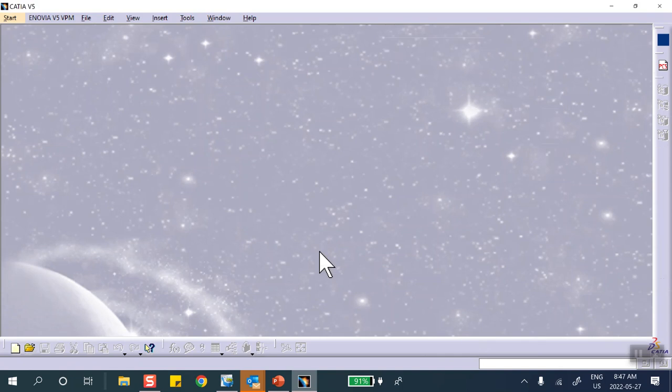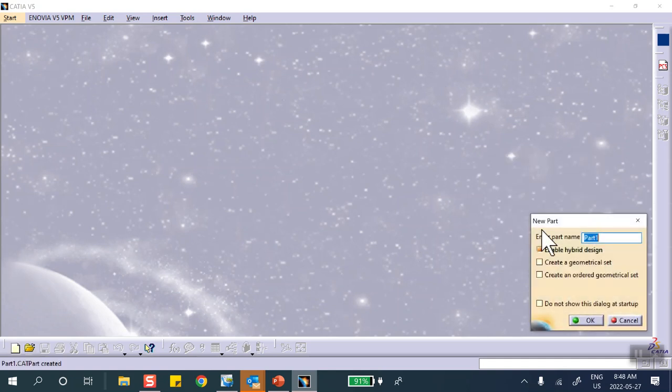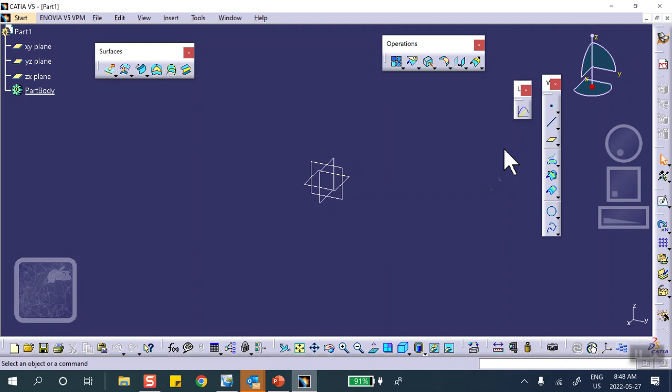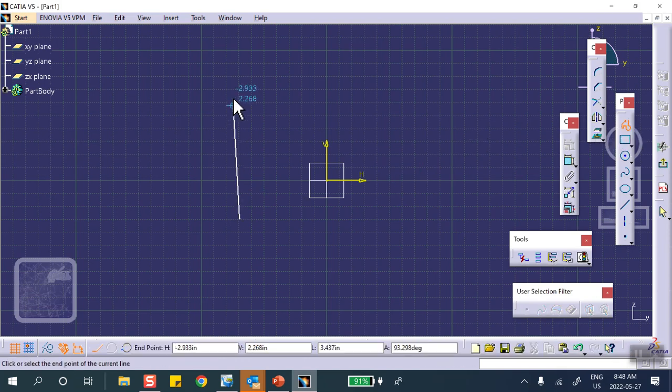Now, from this point on, I'm not going to worry about dimensions. I will just go make it. I'm going to create an extruded L, so that the sides talk to each other and measure. Okay, so let's start with the part file. And you have to be in generative shape design because you're creating a surface. So on that vertical plane, for example, I like to do it on this one. I like it better. So make an L like this.